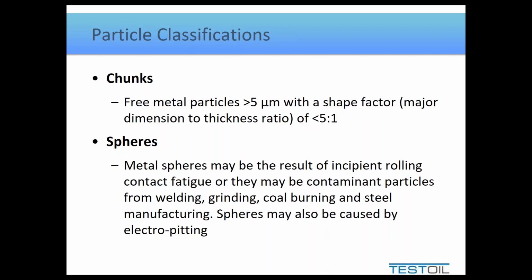We also go on to identify anything spherical. Spherical is an indication of a different type of spall that might form. It is also an indication of debris left over from manufacturing. So under a microscope, we can see these and we can identify them based on their overall shape and color as to what is the likeliest mechanism that created them there. It's important to note that sometimes these spheres are caused by stray electrical charge. So there is a bit of an outside factor there that would be considered absolutely abnormal, but also not that common.